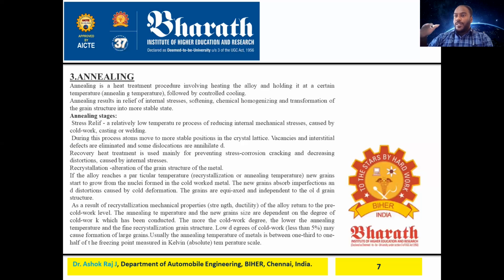But when you do the heat treatment, the arrangement of the atoms will be good. And not only the arrangement: when the arrangement is proper, the vacancy and interstitial defects are also automatically eliminated, and dislocations are also annulled.